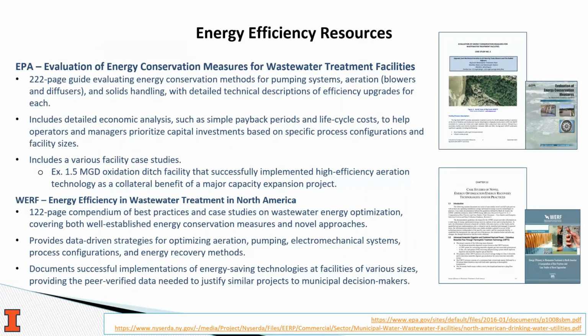And they do include case studies as well, highlighting one, a smaller wastewater treatment plant, a 1.5 million gallons per day oxidation facility in Washington. It highlights how they adopted high efficiency aeration equipment, which had a major initial upfront cost, and it was a part of their major expansion project. But it highlights how their payback period is 33 years, but they've seen significant energy savings already.